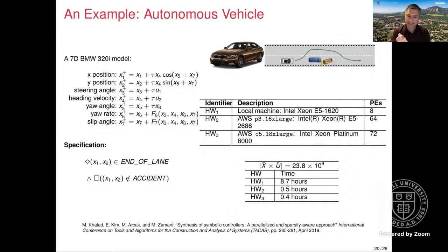And the other thing I want to emphasize is you actually do not need to design those online. You can have a library of these controllers offline. We can call it motion primitives. You can design these motion primitives offline, and in real time online, you can call these motion primitives depending on the scenario in which your car is being driven. Okay, so far it was about discretizing the space, computing a finite state representation of the continuous dynamics. You might say, yes, compositionality was nice, hierarchical approach was nice, but still one might suffer even to build a finite abstraction at the component level, right?